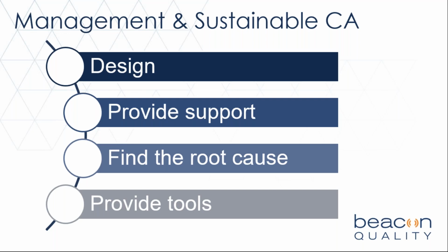Many people forget that it also belongs to the design phase. If you are design responsible, or if your customer is design responsible and is giving you the print, start with design. Start with the design FMEA and see what the flaws are there, and see what led to the process. Is it a process problem? Is it a design problem? Do not leave that area because that's important, and provide the right support where it's required.